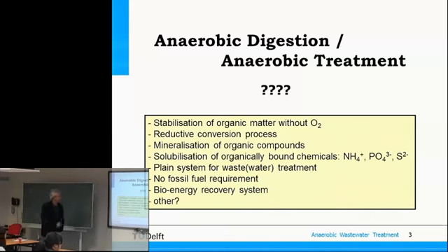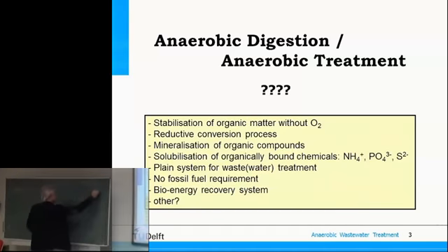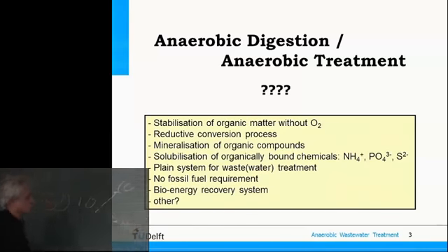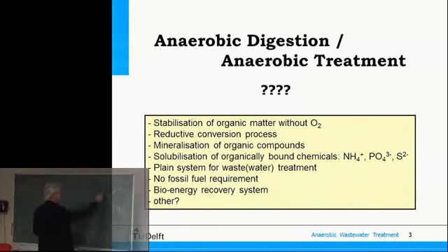This means that in aerobic biological wastewater treatment, organic matter is oxidized. If you recall from the other lectures, COD plus oxygen is converted into CO2 and water. Well, in anaerobic systems we don't have any oxygen, so there's no oxygen present to oxidize all the carbon to CO2. Now, the absence of oxygen means that the carbon itself will be reduced into its final product, methane gas. And that's one of the basic characteristics of anaerobic treatment, anaerobic digestion. So you produce methane gas from organic matter. It is a reductive conversion process.